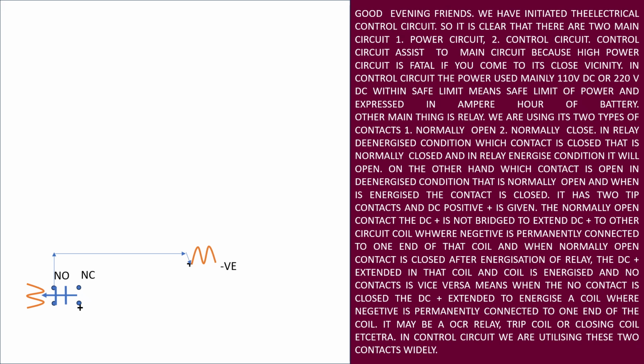If any safety relay energizes, this DJ closing coil will de-energize and the DJ will trip. So this is the use of the normally closed contact in the loco. All the safety relays' close contacts are given in the DJ's EFDJ and NTDJ coil. I have shown you already.